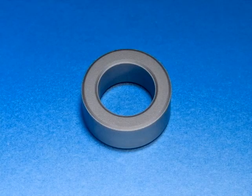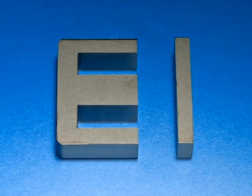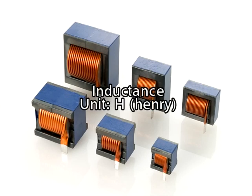A greater amount of magnetic energy can be stored when the solenoid coil is wrapped around a ferromagnetic core. The core itself can take a variety of shapes, depending on the application and voltage current. The larger the current that passes through the coil, the more magnetic energy is stored in the inductor. This characteristic varies depending on the number of loops in the coil, the shape of the core, and so on. The functional characteristic of the inductor is known as inductance and is expressed in units of H, Henry.